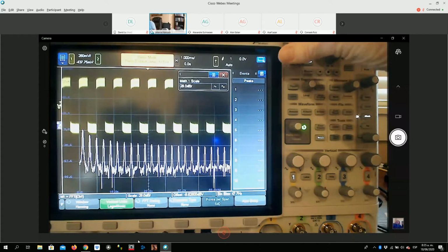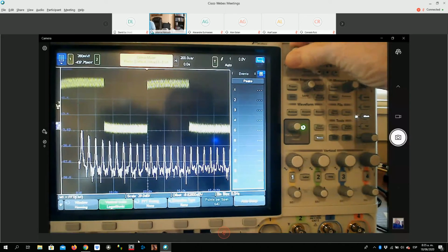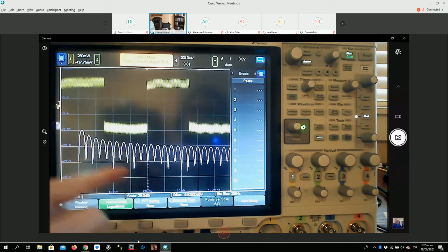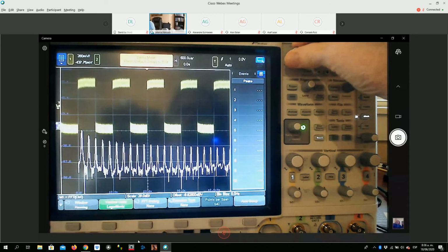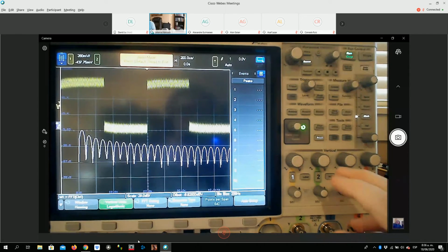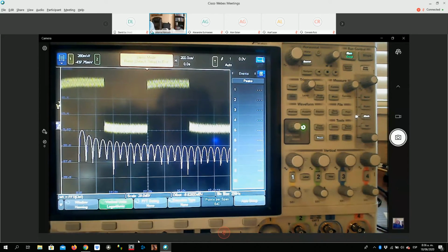Okay, now let's rescale the time base, and let's go down to just 2 cycles. There you can see the lobes. As I scale more cycles, I get better frequency resolution; with fewer cycles, poor frequency resolution. Now let's compare windows. I'm already in the FFT. Over here is where you can select the various windows: Hanning, flat top, rectangular, Blackman-Harris, and Bartlett.